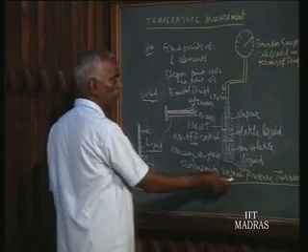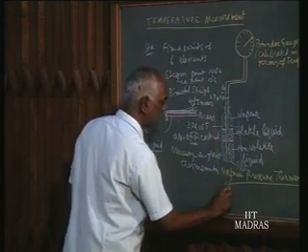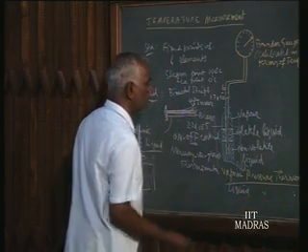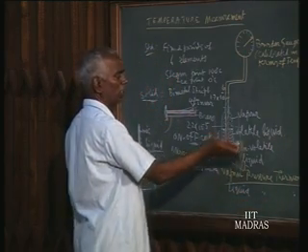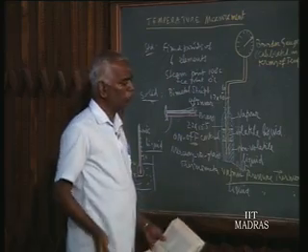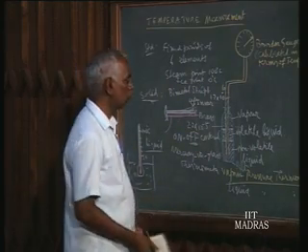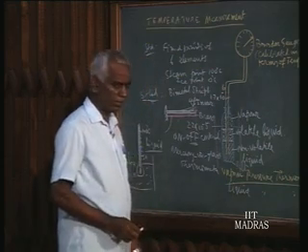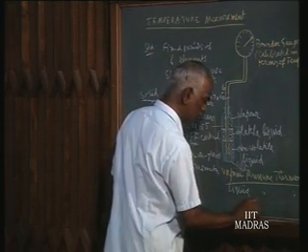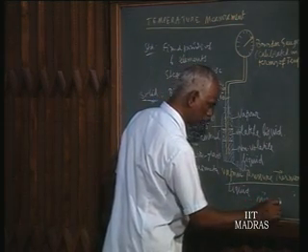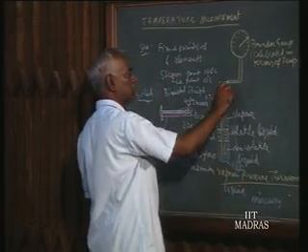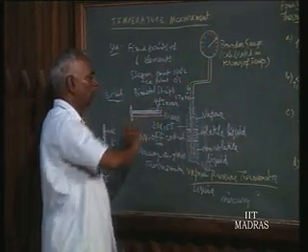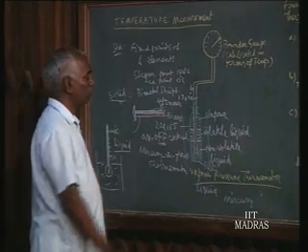There is another version. Instead of this vapor pressure thermometer, there is also the liquid pressure thermometer. There only liquid is made use of. For the volatile and non-volatile liquids, there are some chemical names, you can refer to the standard textbooks. In the liquid pressure thermometer, the whole volume is made up of only one liquid, probably mercury. Mercury also can be used. The bulb and this tubing, the Bourdon gauge, everything is filled up with the liquid.